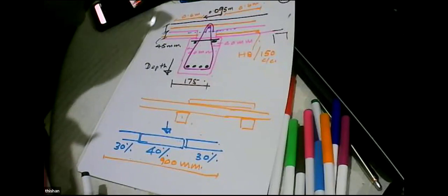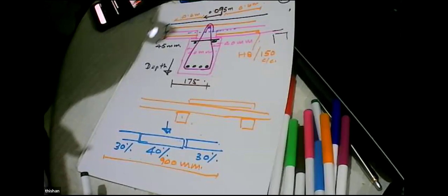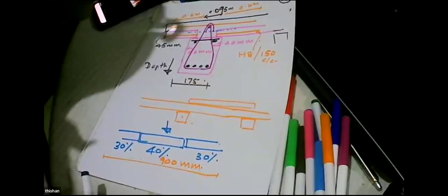Is the imposed load enough, since the above slab load is acting during the casting? No, during casting we have a prop. That's why I said mathematically the whole system is on props as long as we are casting. So without a big huge error, we can reasonably assume that everything is cast monolithically, and we can design the reinforcement accordingly. Is that clear? Yes, that is clear, sir.